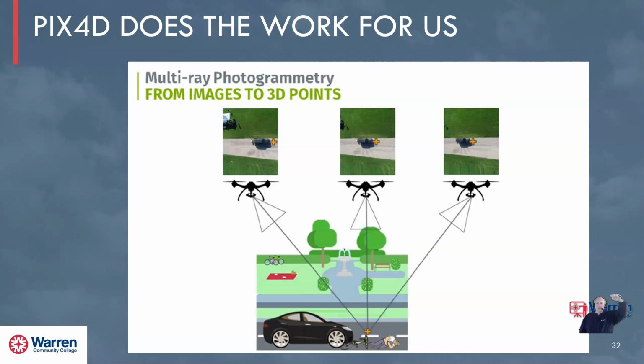You get error from your distance from the images. So this is called ground sampling distance. You get error from parallax. You get error from the angle. You get error from the movement. So what we do a lot in the photogrammetry is we adjust and minimize these errors to get to a more geometrically accurate representation of that area we're trying to define.